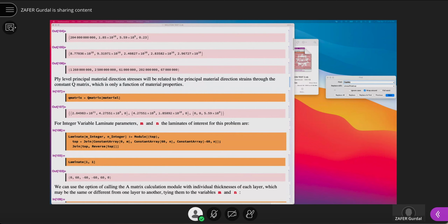The only two things that we haven't done are nothing entirely new, but they are important for composite design optimization. Number 1, different analysis approaches, theories. You need to be exposed to at least one additional theory that takes into account interlaminar stresses between the layers. Nothing we have done so far is capable of taking into account those stresses. So you need to at least go to first order shear deformable theory to get the basic information about interlaminar stresses between the layers that try to actually separate the layers and cause delaminations.